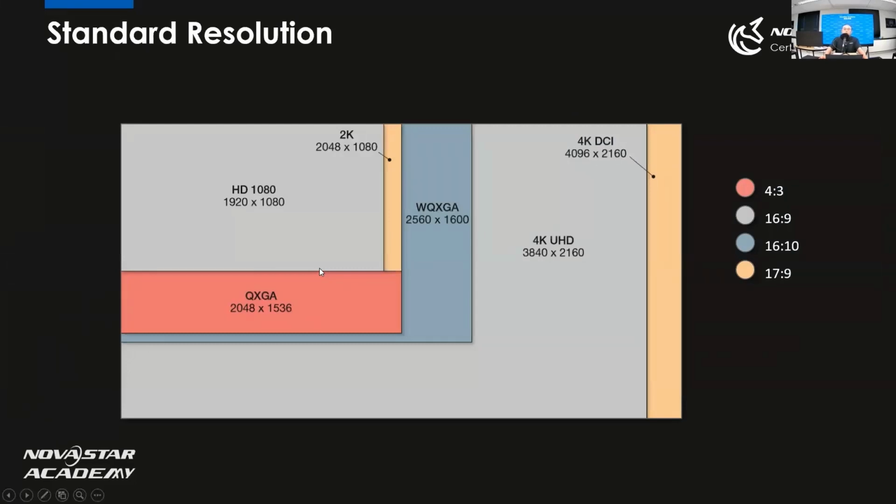And every time when we talk about the resolution, we know the benefits of the LED screen. That is, the resolution we can customize. But here we still want to introduce some standard resolution. As we know, the pixel pitch is getting smaller, so the screen resolution on the same physical size will be bigger. As we can see from this image, there are the common standard resolutions from Full HD to 4K. So that's why we need a bigger device which can handle the bigger screen.